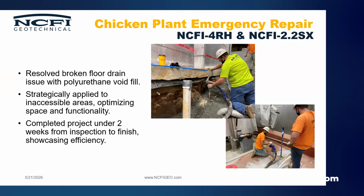And so we went in and we pushed PEX tubing to the center. We had access from both ends of the freezer, and we just basically pumped foam until it came out on the other end, and filled all those voids up to reestablish contact with the soil. That is all we were trying to do there.